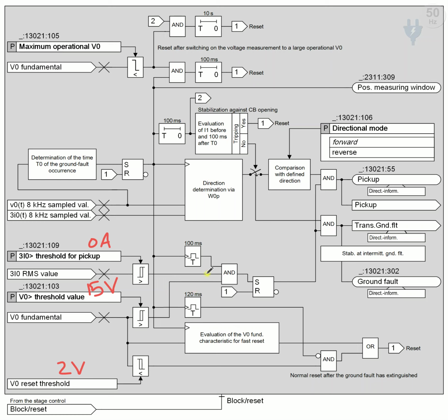The current condition will be high forever, so the effect of the 3I0 will be neutralized. This is for the case where we want only a direction result and don't want any pickup, only to determine the result of the fault.